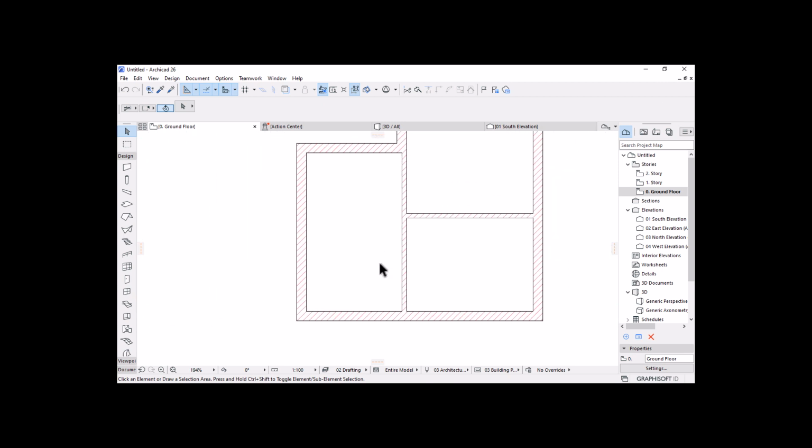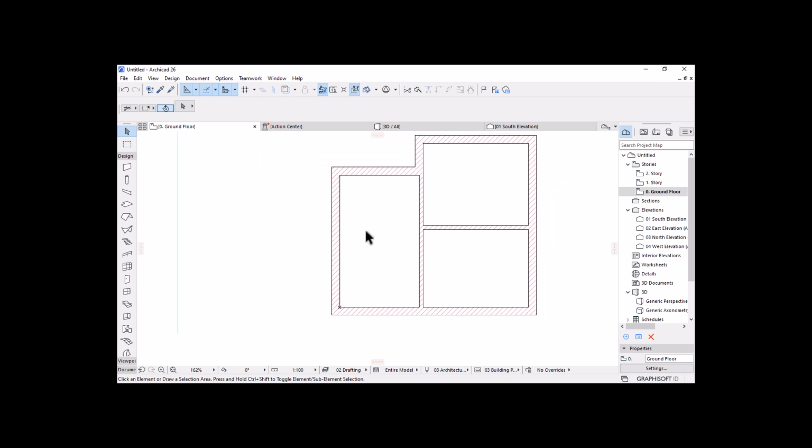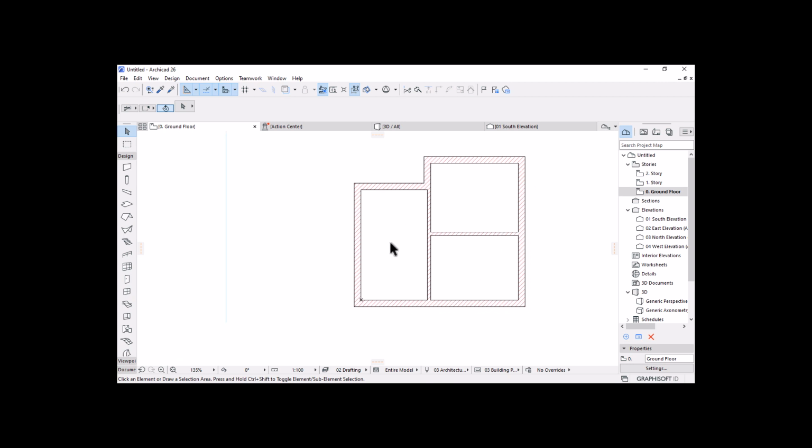All right, and then this area is the bedroom, and then this side is the closet, and then this side is the en-suite. So as it is, I see my bedroom is too small, because you could see the closet is bigger than the bedroom. So I need to confirm some measurements here. So to confirm measurements in ArchiCAD, we use a tool called measure. So to activate that tool, you could hit M on your keyboard.